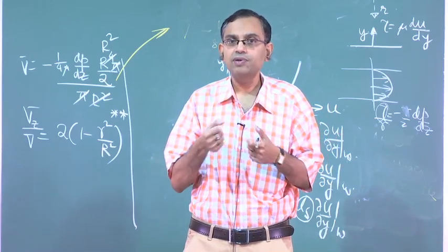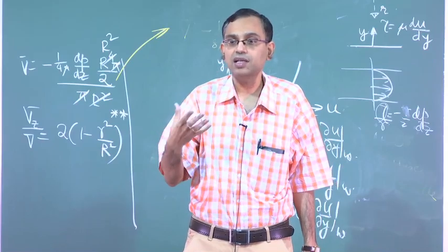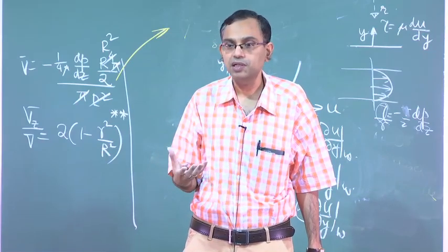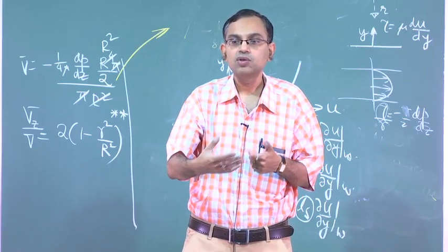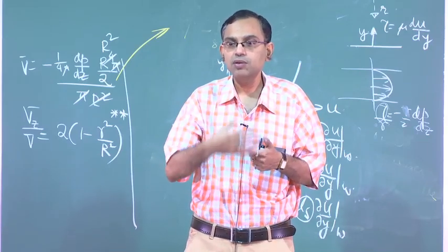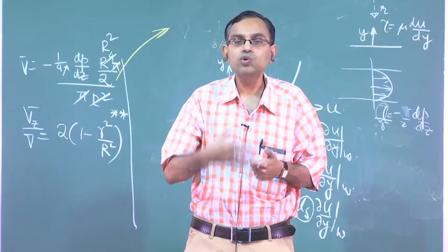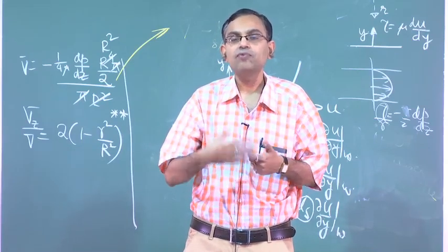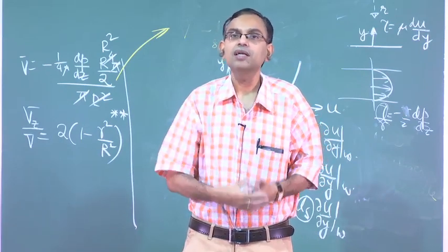Instead of creating a positive displacement pressure gradient, you can use surface tension to generate the equivalent pressure gradient, because surface tension is a beautiful force at small scales. So, in our next lecture we will see what surface tension is and how it can be used to manipulate a flow which is fundamentally pressure driven, but the pressure gradient is created by surface tension.